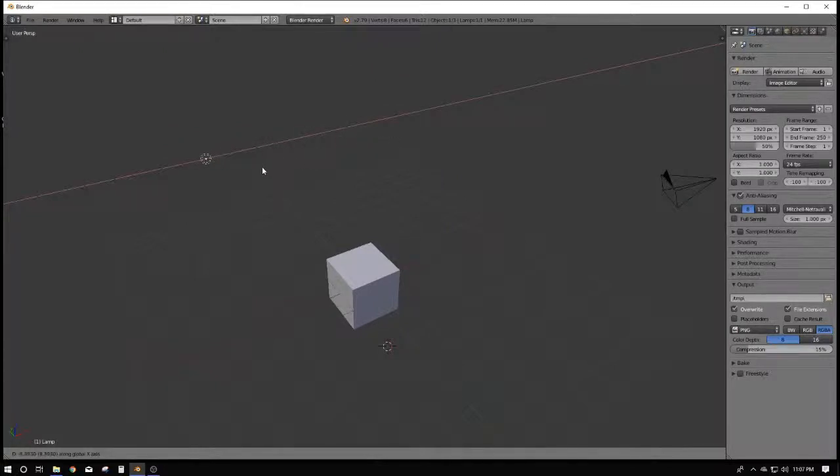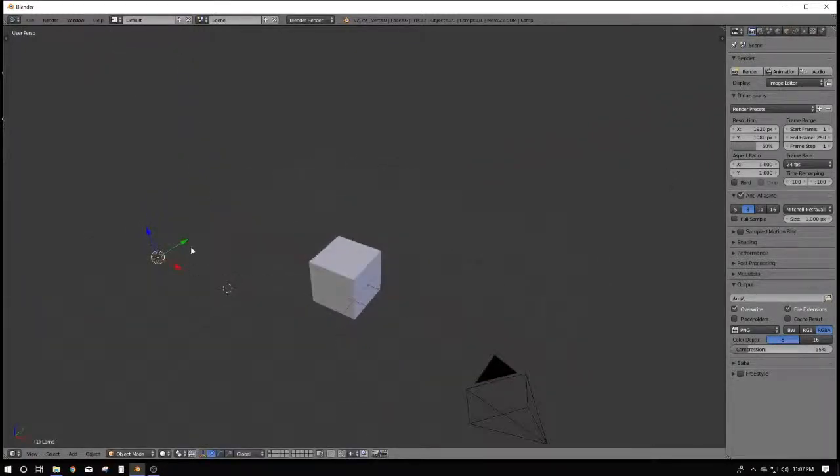So you'll have to go across, click G, middle mouse button, Z, click G, middle mouse button along the Y, click, and move it that way. And that's just a little bit faster and gives you a little bit more exact movement than always choosing to move it with these. So whichever way you decide to move it, it's no problem. It's up to you, really.